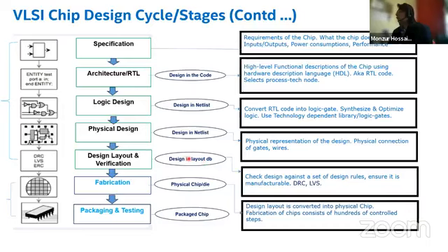So up until now, your design phase is done on your computer. Now what you will do is send this layout into fabrication, or in short we call it fab, and then it will become a chip. Okay, so then you are moving from the designer's hand to fabrication. When chips are made in the fabrication, a lot of steps happen. We have a talk on this part. Our presenter will give you a talk on how fabrication happens. And at the last part, you package your chips so that it is a nice shippable package chip. So that is your VLSI chip design cycle.